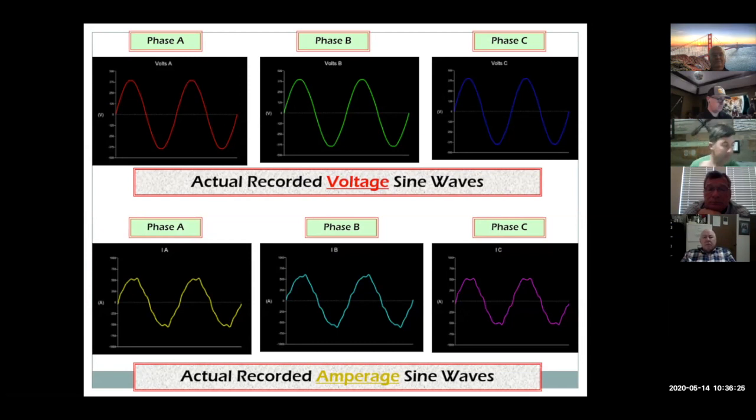And those of you that's been into this, you can see because this sine wave has dimples up on the top, they're not flat. They should be nice and pointed, but they're not. They got distortion up there, and so that is harmonic distortion in the system. Sometimes this causes a problem. In this case, it didn't, but if it was dealing with some sensitive equipment, this would be very important.